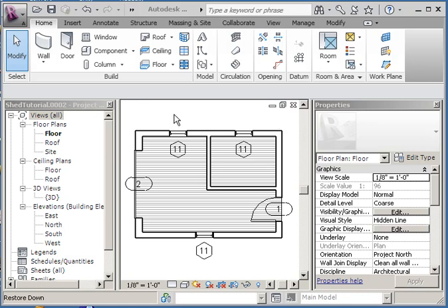But before we go, I think I need to talk about these tabs and labels here. These labels are designed so that you can easily make a door and window schedule. A schedule of parts that are duplicated, like the hexagonal symbol here for the windows, all have an 11 in them, and that means that each one of these windows is exactly the same size. So you could put it once in a table called a schedule and tell them how many of those particular